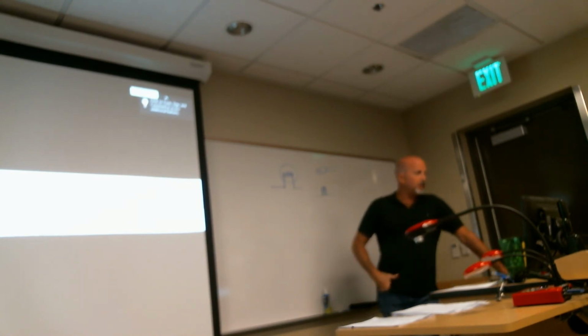So wired terminal lugs should be used to connect wiring to terminal block studs or equipment terminal studs. No more than 4 terminal lugs. So this would be a terminal lug, just like some of the battery connections. Battery cables in your car, some of those are like that. Like a DC bus should be connected to it? That would be a terminal lug on a bus. So a bus would be a strip of metal with bolts on it, and most of the time they're grounds, common grounds.